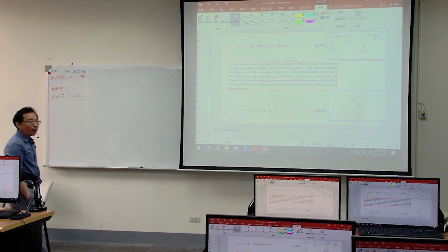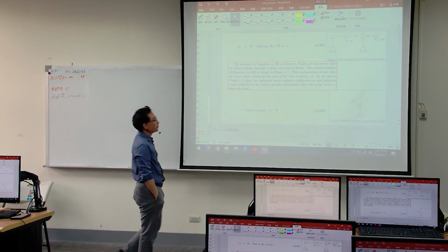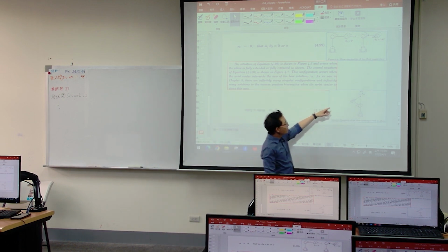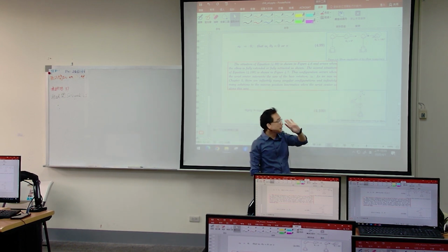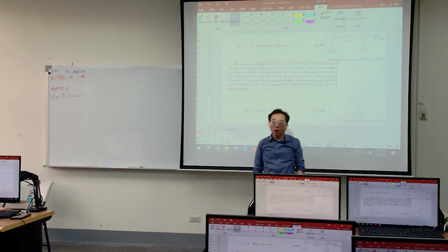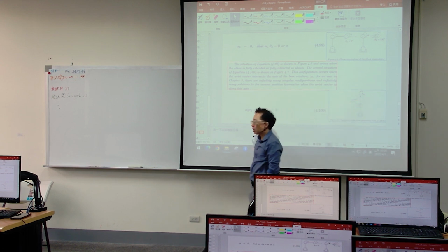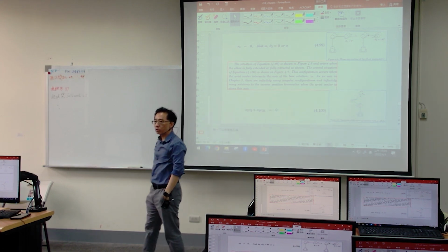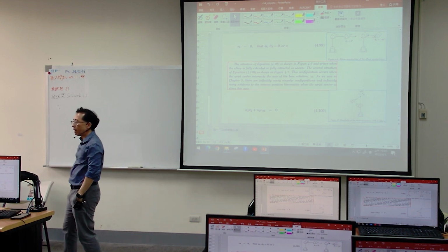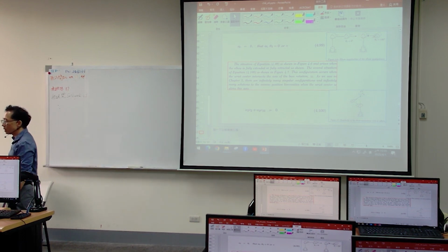For the bottom case, it's easy to explain. When you rotate arm 1, you will find out the end of arm 3, its coordinate, did not change. I did rotate, but it did not change. Singularity. So that's what I tried to mention.